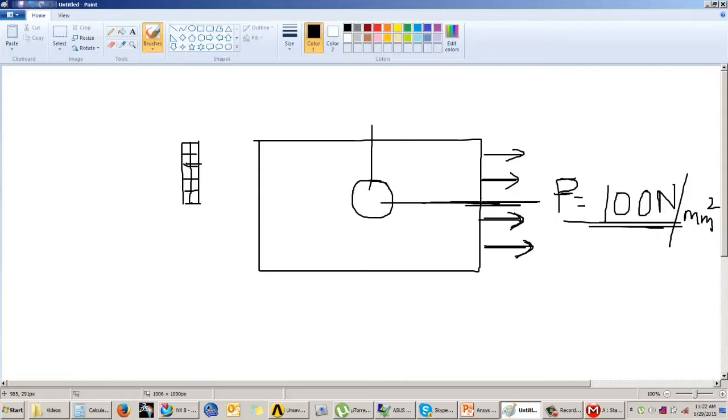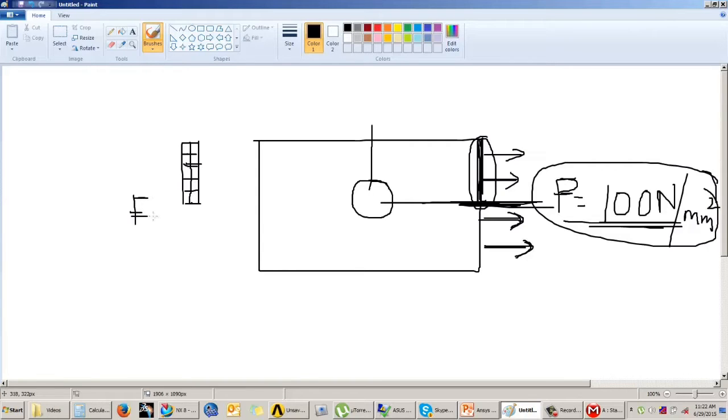As the area gets divided, automatically the pressure will also get adjusted, and it will get applied on this much area. But when it is with respect to forces, forces will not get halved. Forces will remain 100 Newton only, but it will get distributed only amongst these nodes. So automatically the load acting on these nodes will increase. But when it is pressure, pressure gets applied on the area.